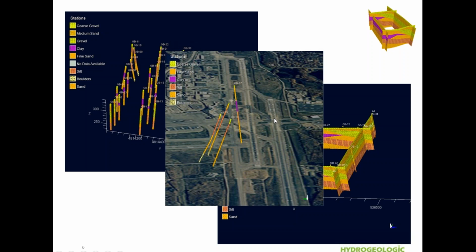So as I was mentioning, you can also display deviated or non-vertical wells. This information that's stored in the drilling protocol table, the inclination and the azimuth, are used in order to display your non-vertical or deviated wells right in the scene viewer.